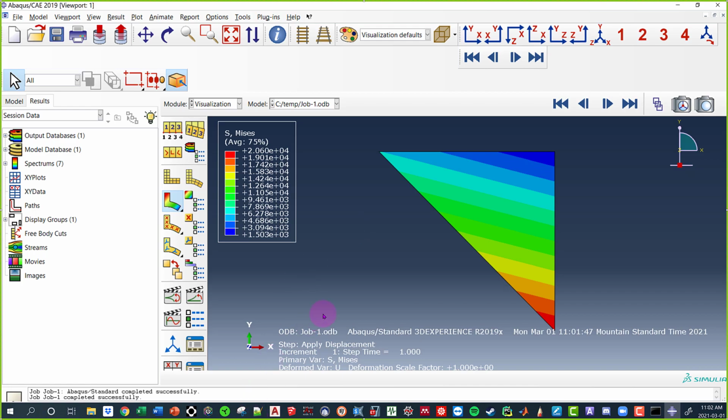In your assignment, the element's bigger than that, so it's not going to have this weird shape. After we do this, all we're going to do is look at the reaction forces at each one of the nodes. It's kind of hard because I don't have my probe value, but you are basically going to probe the 4 nodes, and whatever those reaction forces are, that is your stiffness entry.